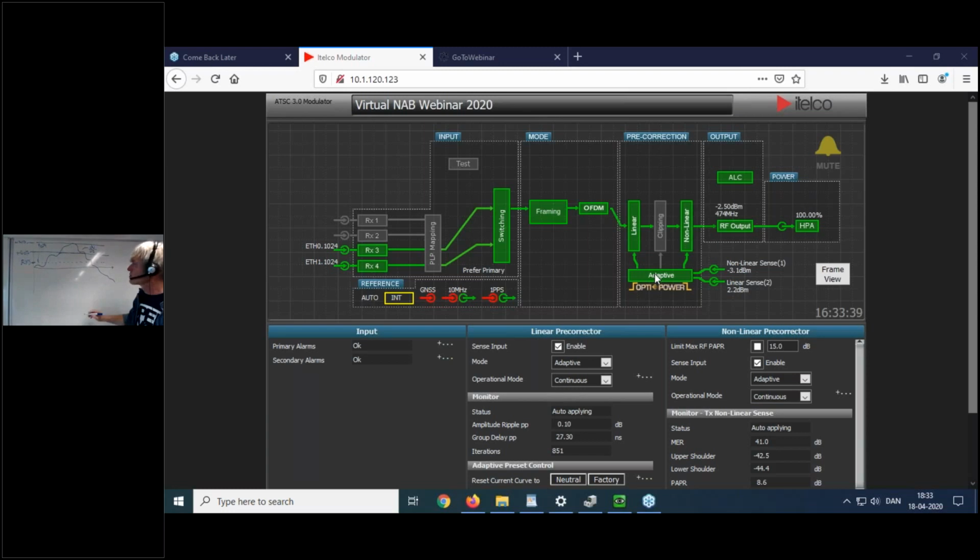If we look at the equivalent in the frequency domain, we take the Fourier transform. Let's say we have an OFDM spectrum without any peaks. When we create discontinuities, you all know the signal begins to resemble more and more a square wave, and the Fourier expansion of a square wave has a lot of odd-order harmonics.